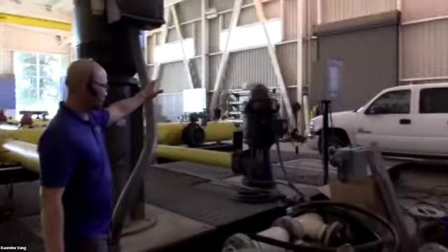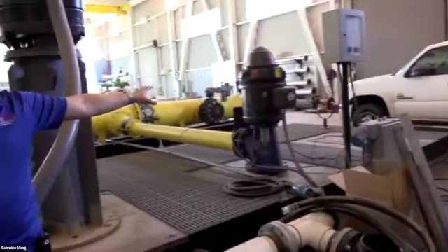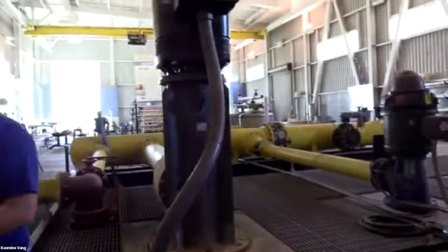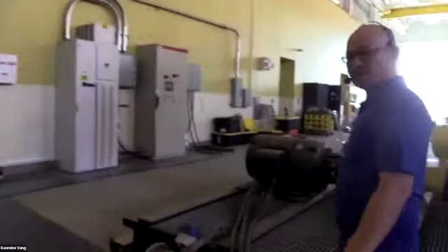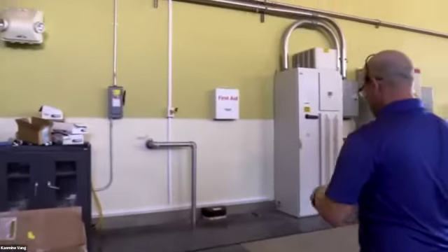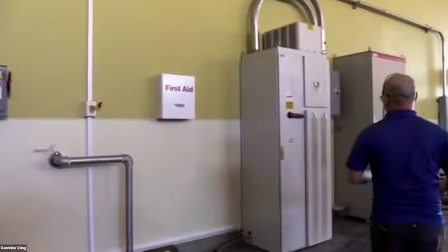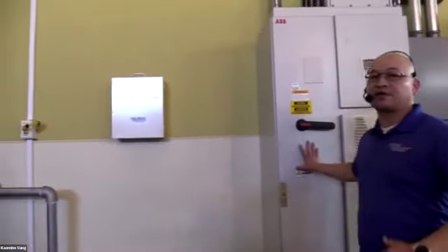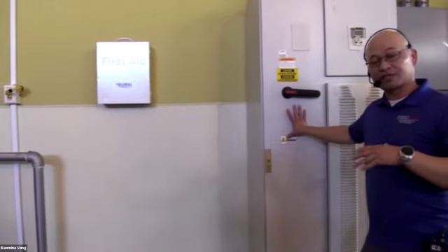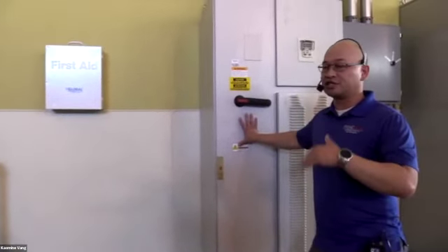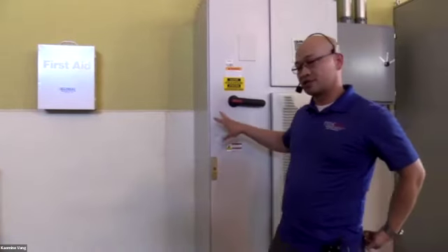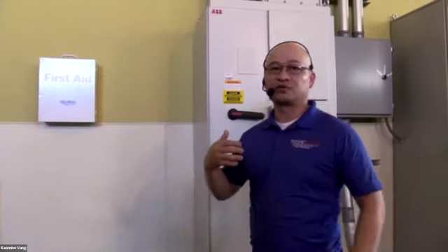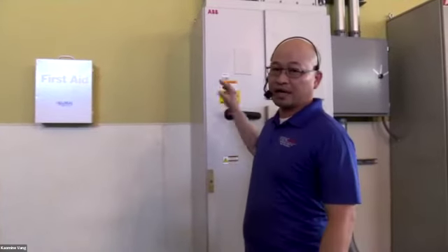And then we also have a 50 horsepower motor over here on the right, my left, but we also have a booster pump if we needed more pressure here. So what we utilize is these big VFDs, or variable frequency drives. When we run the pump and we want to reach different operating ranges, flows, and pressures, that's when we change it. For us, because these units are big, we have an application on our phones that we can use to operate the machinery or the mechanism in the VFD.